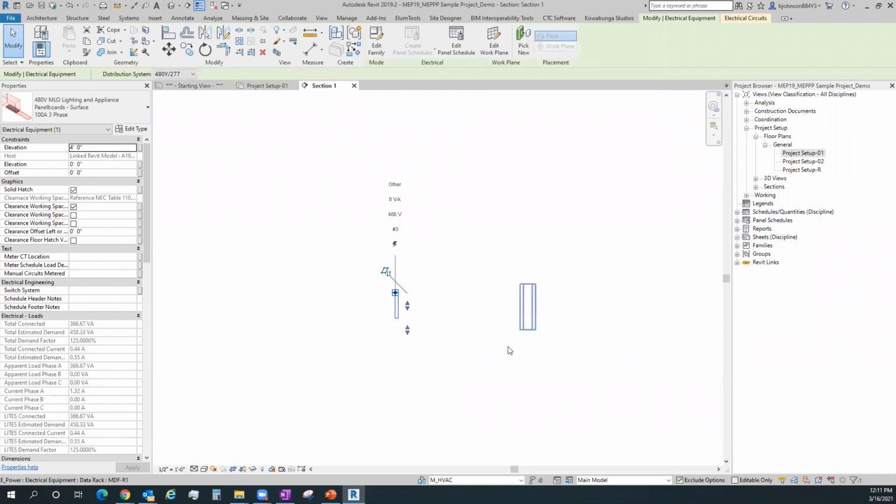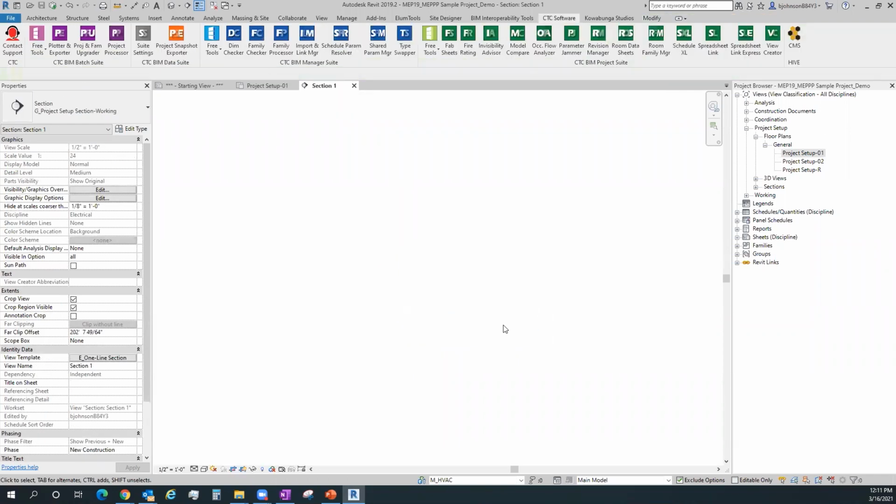So that's a Revit trick that we can use to leave an object intact in place and not see it in the view, without actually hiding it from view or turning it off, as with our little sunglasses here, or going to visibility graphics and literally turning the object off. So everything else in my view is hidden except for these objects. That plays a big component in how we get to one-lines inside of Revit.